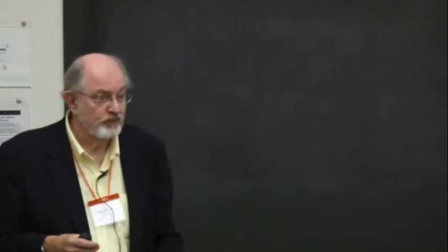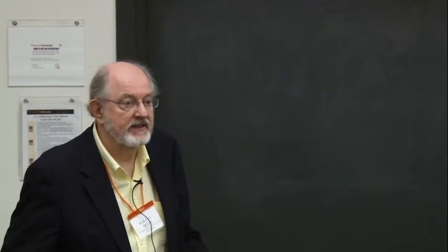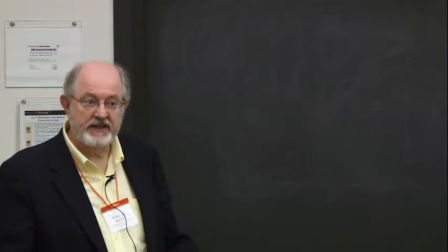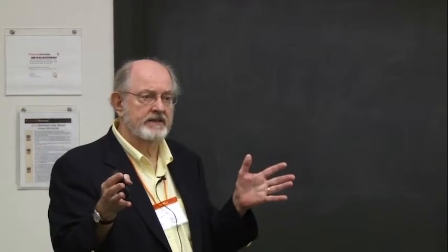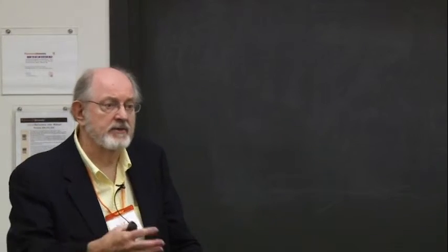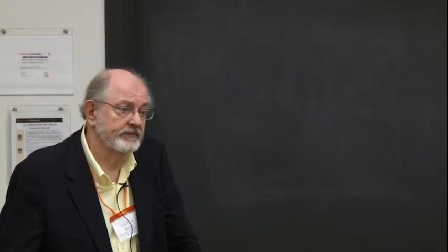I'm in favor of identifying the NOC from the first reference mode to be around some kilohertz. 6 kilohertz, I guess, in this engine here. Yeah, I'm showing your previous slide. But I'm wondering if there's any physical chemistry explanation for the number. That number is just wave propagation across the chamber. I know the speed of sound. I know the diameter. It's got nothing to do with the fuel. It's just the geometry and the temperature, because the sound speed depends on temperature.